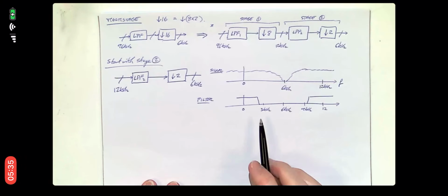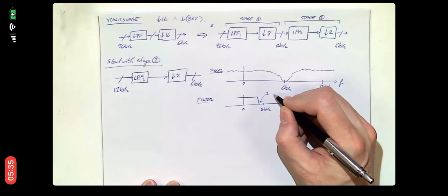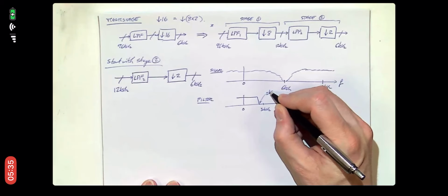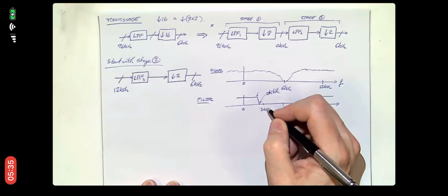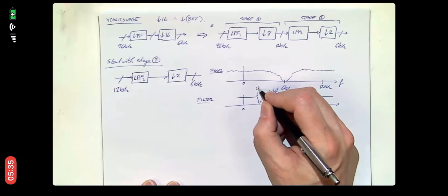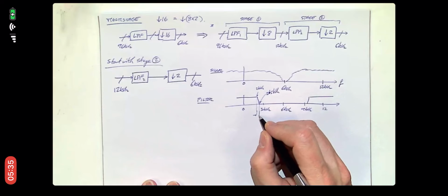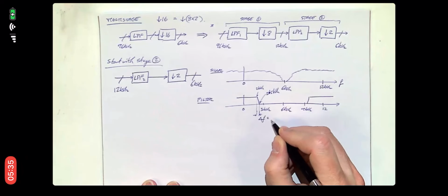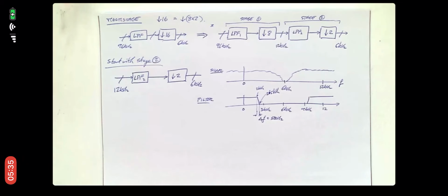And actually, because of what we had specified before, we're going to want that filter to cut off by 2.5 kilohertz, and the F1 edge to be 2 kilohertz. And so this is our transition band here. Delta F is our 500 hertz. So that's our transition band for that filter. So this matches the filter that we wanted for the far end.